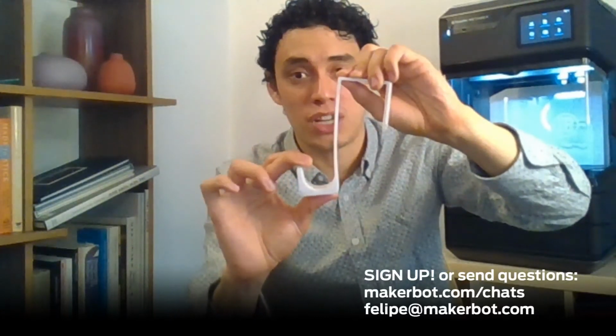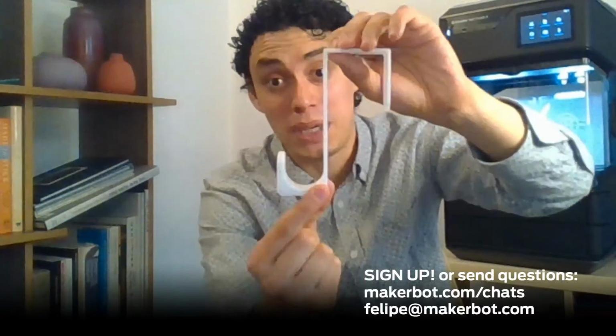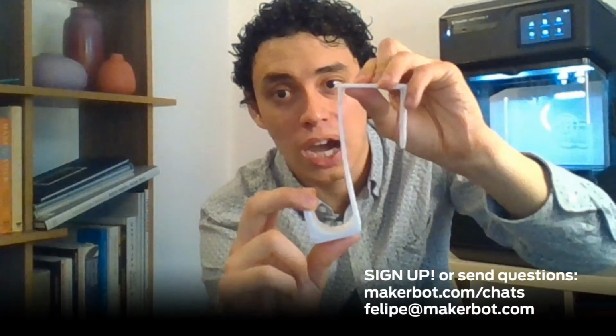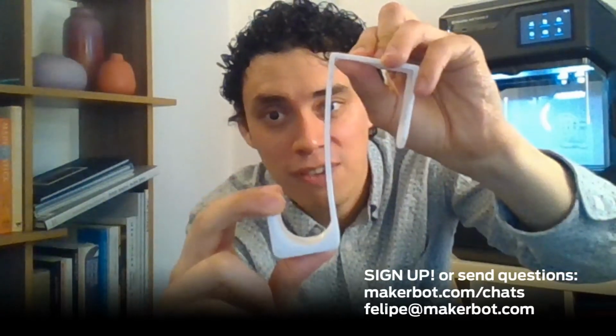You can see how as the stress builds up, tension will start appearing both in this corner and in this corner. In the lower corner, I don't really have a lot of issues because there's enough beef in the material to withstand that stress. In the top corner, however, you can see how fast that part will try to fail. And even though I'm using polycarbonate here as a material, so it's also white, but it's cool for the bathroom. It's a strong material, but it has its limits as any material.